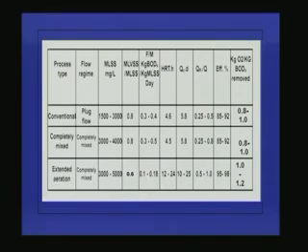And if we talk about the efficiency of extended aeration system, the efficiency varies from 95 to 98% because we are giving so much aeration. So, entire organic matter will be getting oxidized. So, this is the summary of activated sludge process. And while talking about the oxygen requirement, definitely extended aeration system will be needing more oxygen, around 1 to 1.2 kilogram of oxygen per kilogram of BOD removed is required because everything is getting auto-oxidized. There is no need of any further sludge treatment.